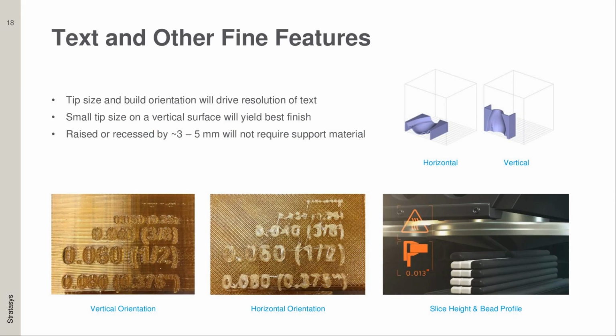Other things that I think are often overlooked with tooling is labeling. It's really expensive and hard once you've machined out your tool to etch in the label and make sure it's serialized for your process. You can add that all in using FDM. A word of caution though is be mindful about how you're doing it. So again, orientation plays a big deal, like I said.